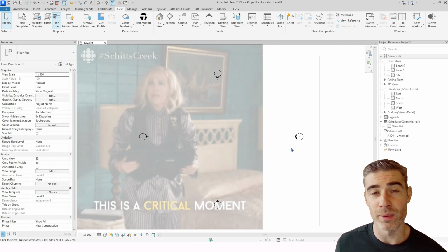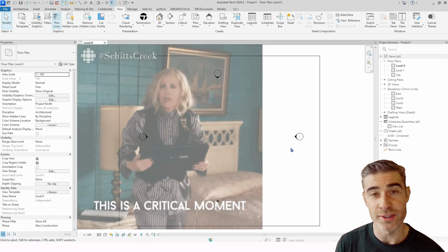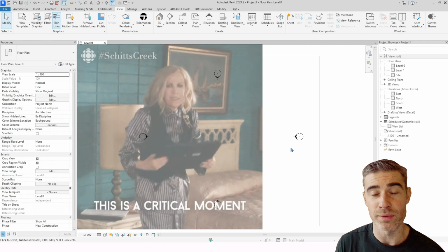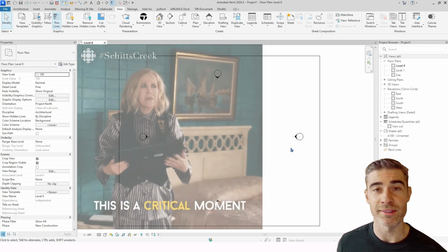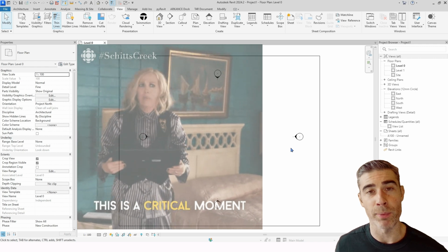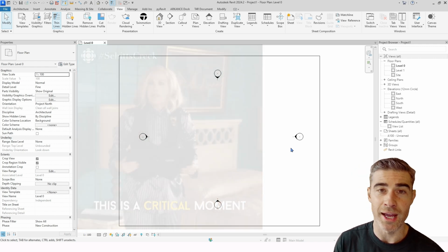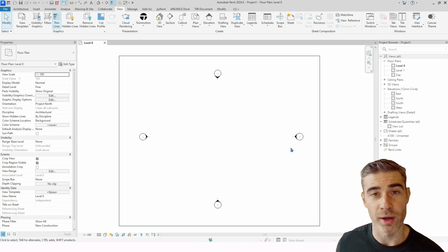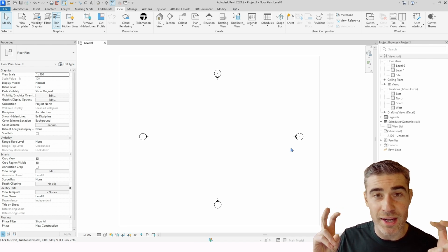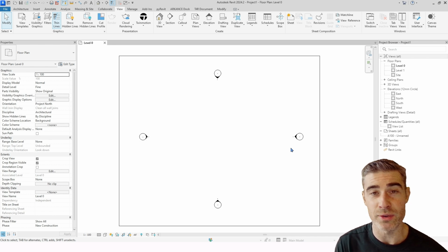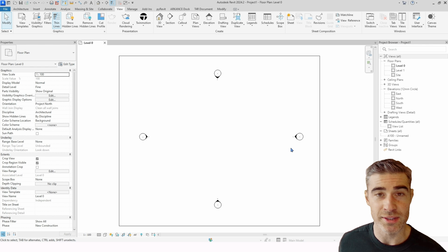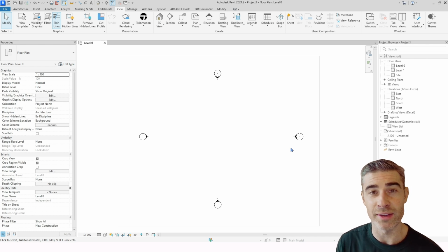Now, the most important step right now is to not do this in your active project. Create a new file that you're going to do this in, because this is the part of Revitizing it properly. If we didn't do this step, when you bring it into your active project, explode it, and start to Revitize it, meaning you're changing the layers from CAD and creating actual object styles, using Revit objects and layers, you're going to start to pollute your drawings. And with every detail that you bring in, the more you're going to pollute it with annotations, dims, and layers that you're not going to want.